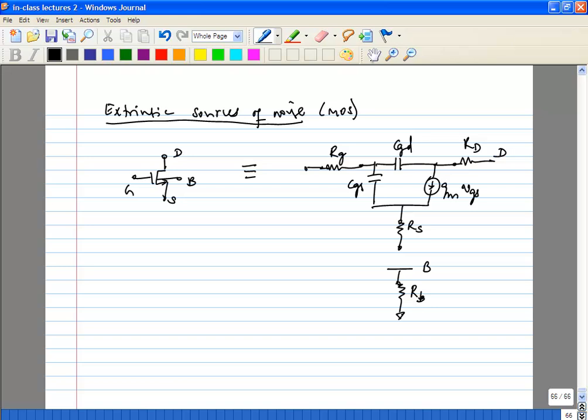Normally what do you assume? You assume if it's an NMOS, your bulk is ideal ground, and in this case you are probably going to design with ideal supplies and ideal grounds, and that's probably okay for a first level class. But if you are doing a real design, you have to worry about all of these things. In your case, you will definitely have to worry about RG. So let's look at that first.